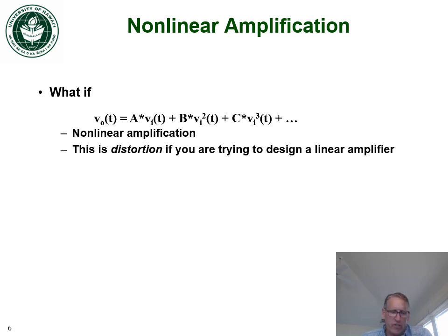All right, how do we describe nonlinear amplification? In practice, all amplifiers are nonlinear. Sometimes the nonlinearity is small enough that we can ignore it. It depends on the application. But typically, nonlinear amplification is described by a power series.